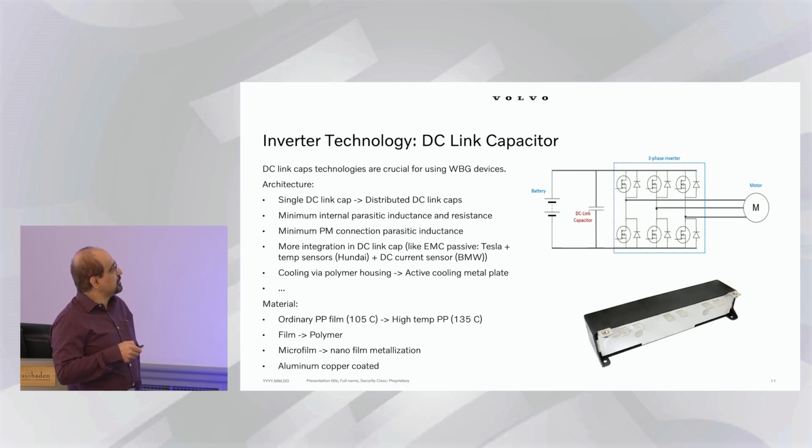And that is especially for the EMC passive, since we are going to use the wide bandgap devices. If we don't make that very close to the terminals that we have here, all the bus bars could act as antennas and send the noise outside.